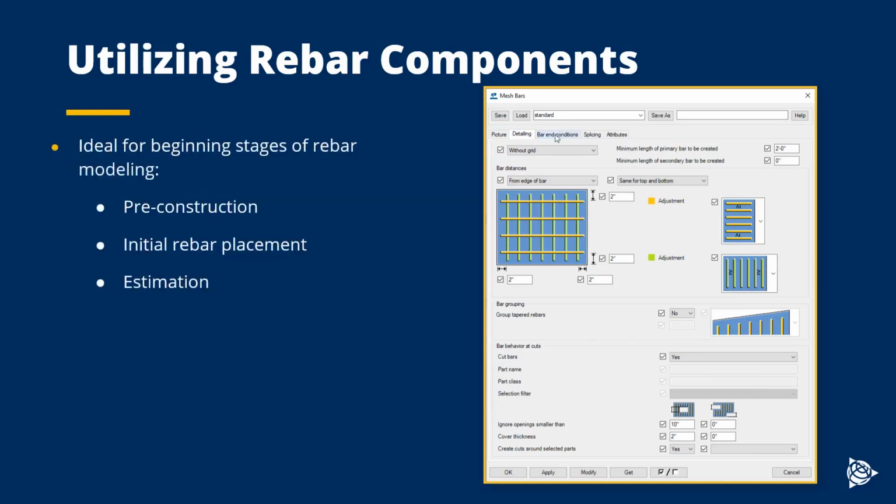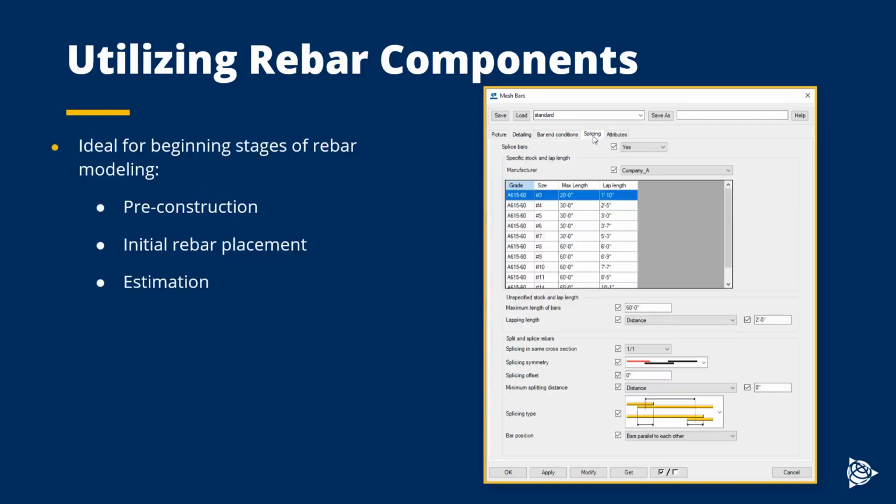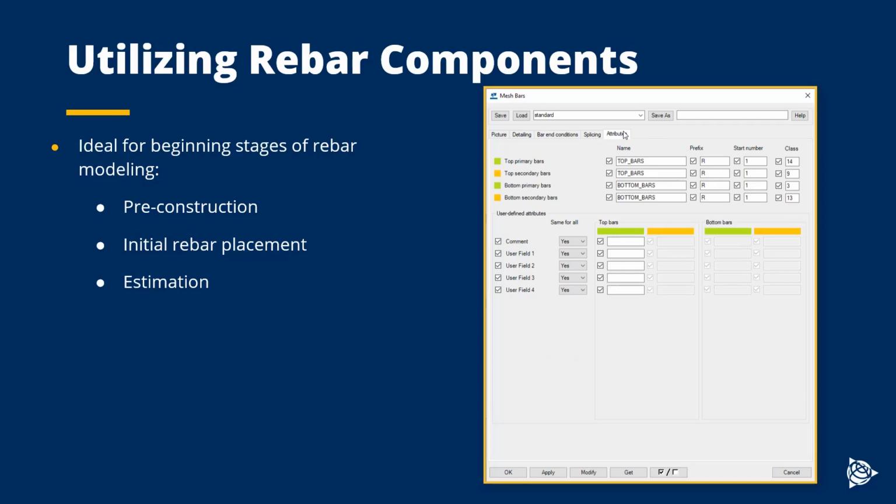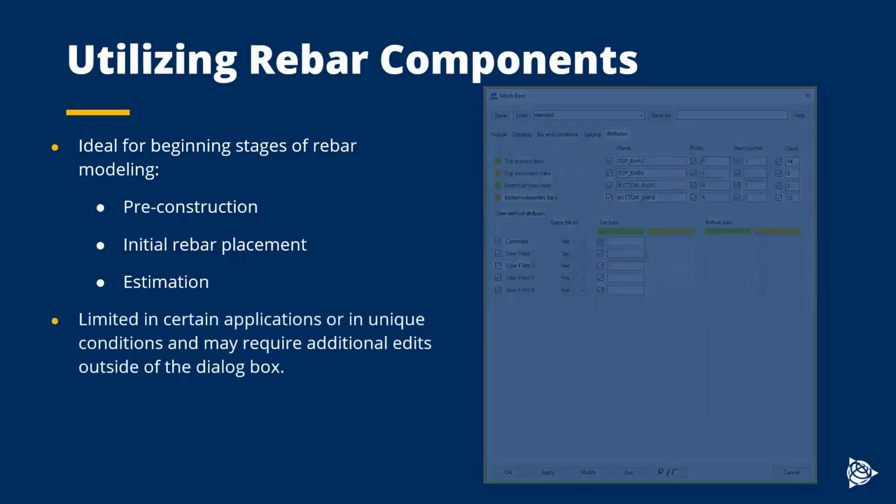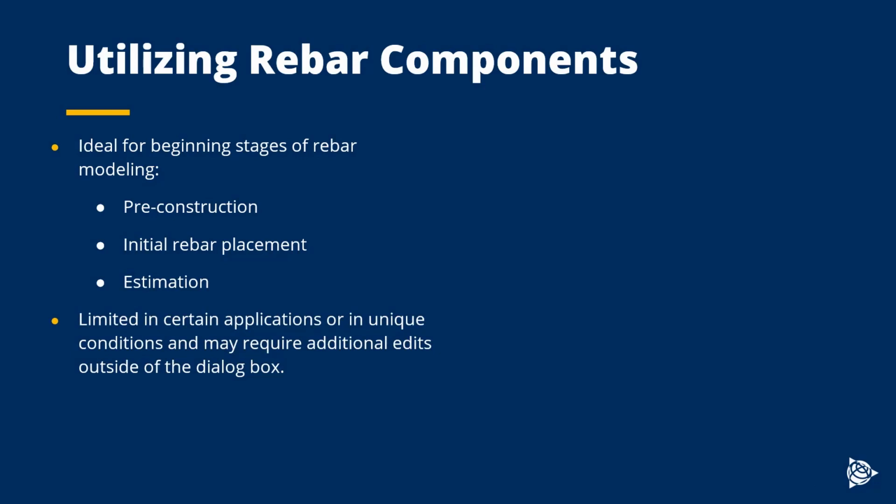Rebar components are ideal for the beginning stages of rebar modeling, whether that's pre-construction or just initial bar placement, or even just estimating how much bar may be required on a project. It's important to keep in mind that rebar components can be, in certain applications, a little limited, and they may require additional edits outside of the dialog box, which is easy to achieve after placing the component initially.